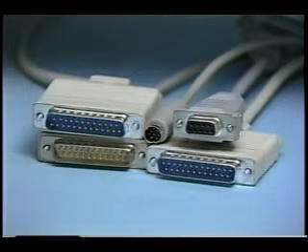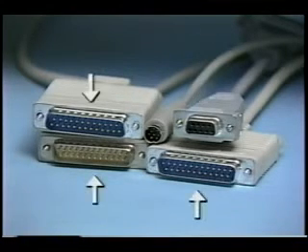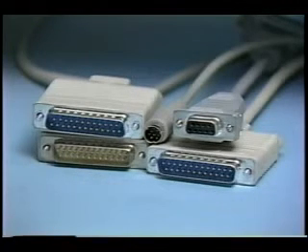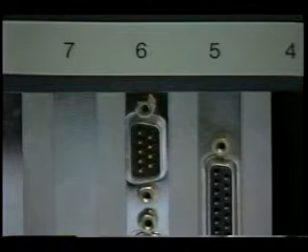For RS-232 terminals as well as IBM and compatible PCs, these cables have a D-shaped connector with 9 or 25 pin positions. On Apple computers and Epson printers, these connectors require cables with a round 5 or 7 pin connector on the equipment side. Like phone systems, not all devices use all pins. Only 4 or 5 of these pins are important to the vast majority of applications. IBM AT-style PCs, for example, all use 9-pin jacks.